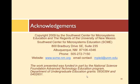Well, that's a really interesting question. So make an energy harvesting device that's big, based on the same thing as a cantilever. It might get too stiff the bigger you go, and the frequency it resonates at gets slower the bigger you go. Well, you'd be trying to find something producing a large frequency, which not very many things do in the macro world, right? There's a lot of tiny, smaller frequencies in the micro world going on. Well, you can run at a higher frequency the smaller you go.